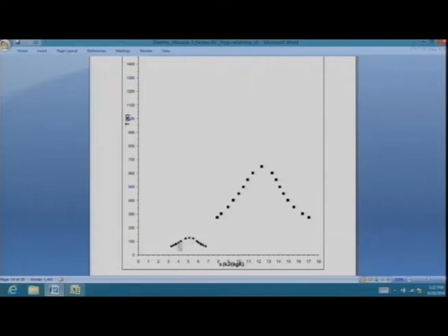So here is what you see. This is nitrogen, the TS diagram of nitrogen. This is the TS diagram for water. And what happens now is, let's take the case of an inlet of a gas turbine. I've been mentioning that temperatures there like 1400 Kelvin, 1600 Kelvin are now typical in aircraft engines and also land-based power generating units. If that 1400 Kelvin is over here, then for nitrogen, we are way, way far away from this saturation dome. In fact, even if you look at water at that state, we are still far away from this.